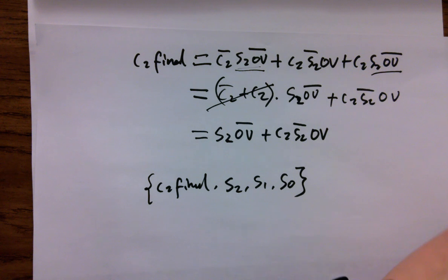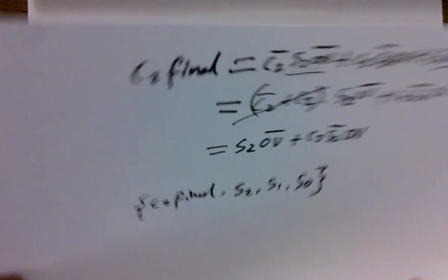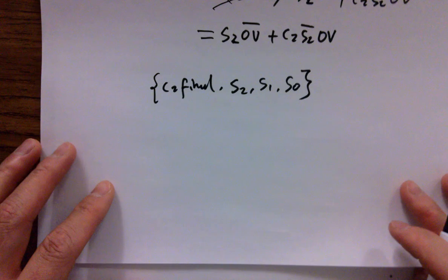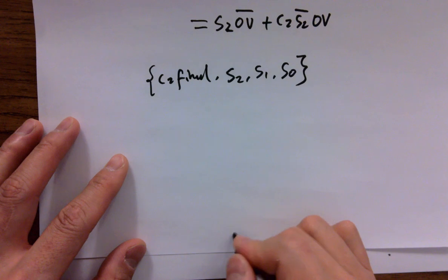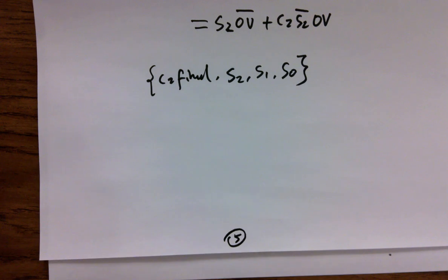So how do we design the system in Verilog? How many modules do we need? Just a top and an adder. So yeah, we need an adder first, right? We can make the adder a 3-bit adder, no problem. It's just a vector when you declare it as a variable.